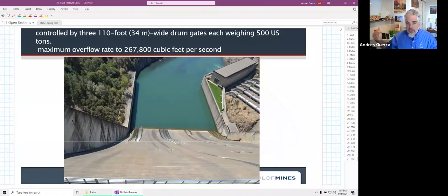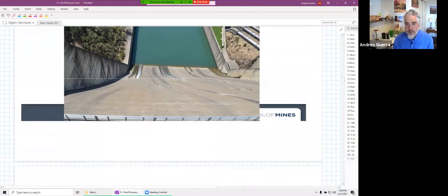It's where in the Sierras, they get dumped on with snow in one day, maybe 5 or 6 feet of snow, and then it warms up, and the next day they get a big rainstorm, and that rain falls on the snow, it melts the snow, and now you get all this water rushing down into the reservoir. And so they need to be able to release it so it doesn't overtop the dam. So that's why they have that spillway